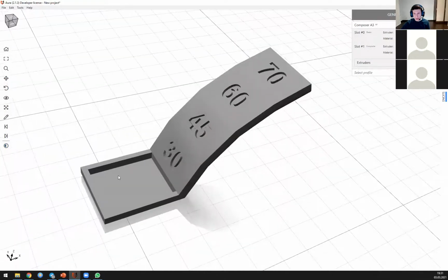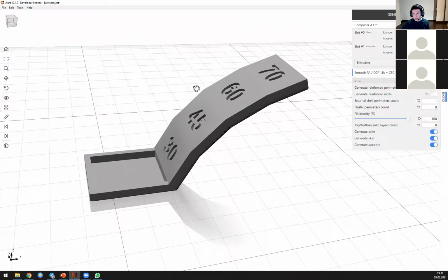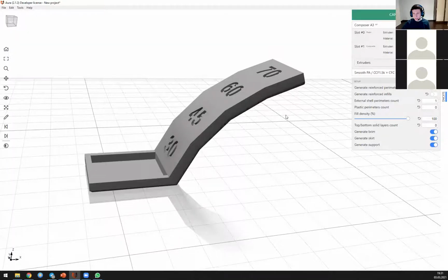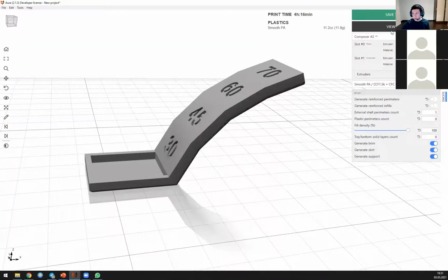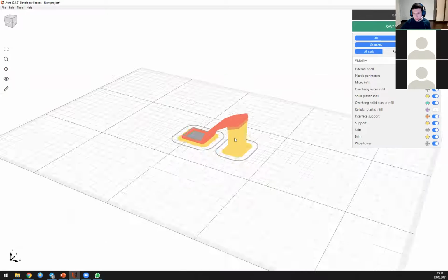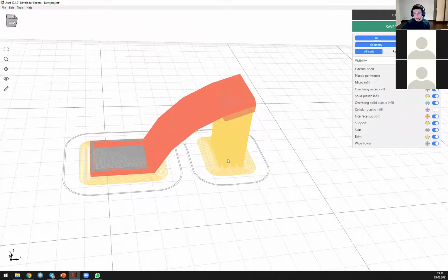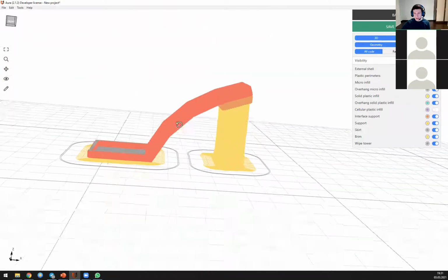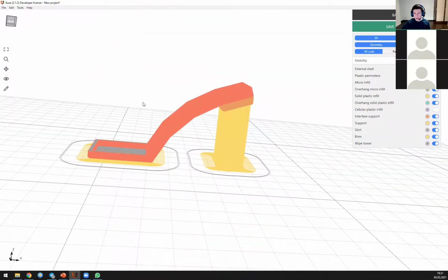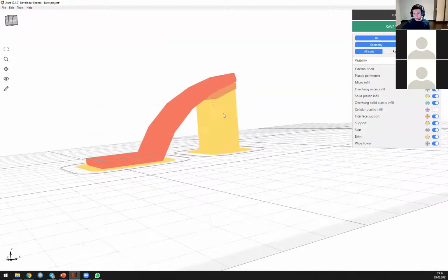It's an overhang test, and if I select the profile and generate the code with the support structures, I'll see that the supports were automatically generated in this overhang area, and the zone for support generation was calculated automatically based on the overhang distance that you can specify in the profile.